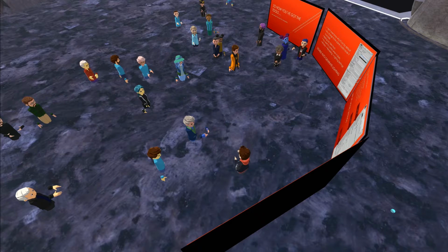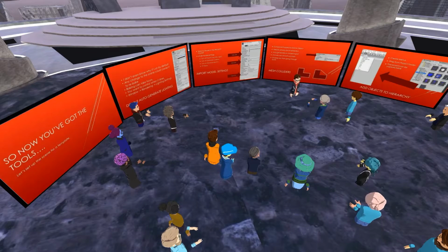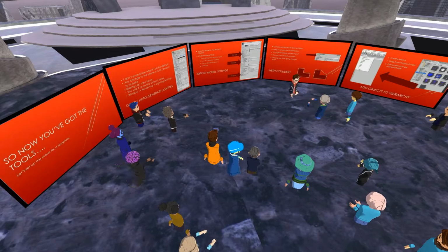So yeah, Unity can import STL files. The problem with STL files is they're typically very heavy. When I'm 3D printing an object, I want to put a lot of details into the geometry, and I want the geometry as high a resolution as possible. That's going to make a very heavy model when I bring it into Unity. It's also not going to have any textures on it, and it's not going to have any UV maps, so it's always going to be a solid color. But aside from those two things, yeah, you can use STL files.